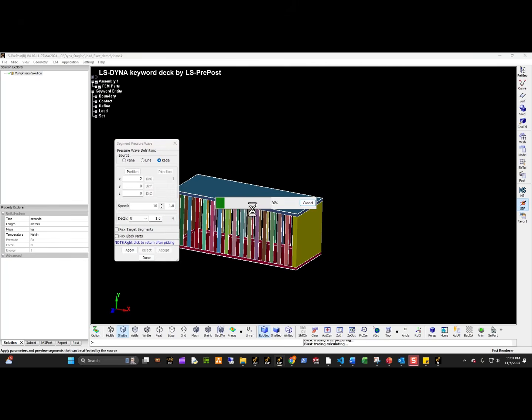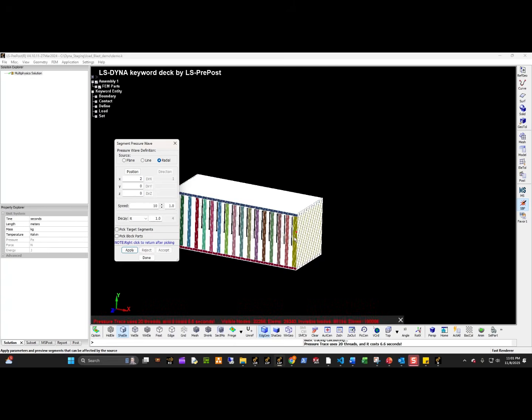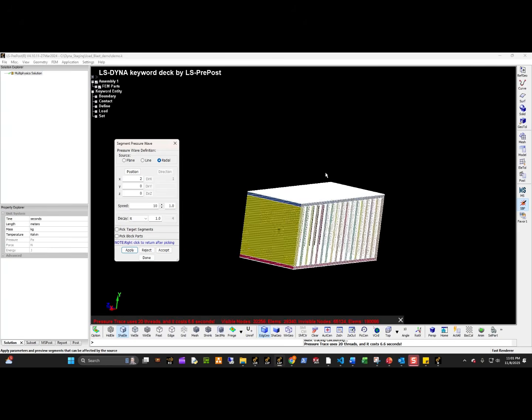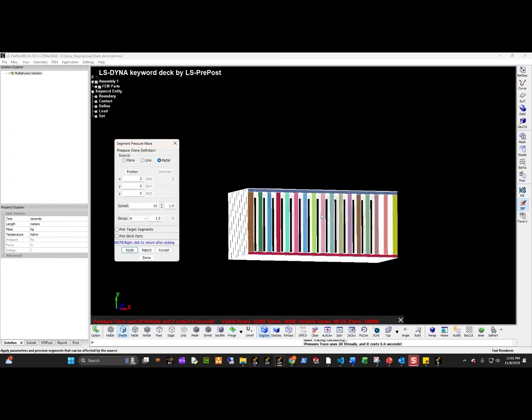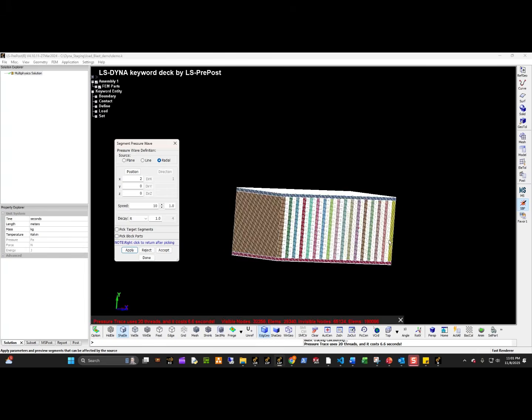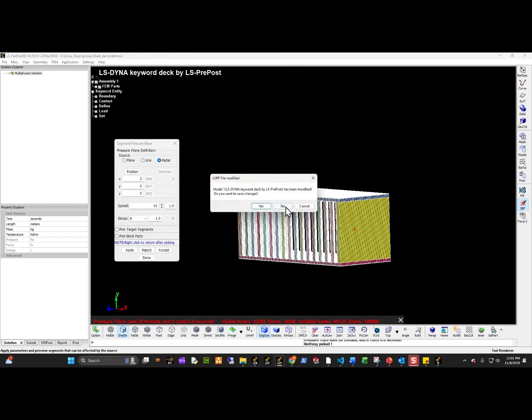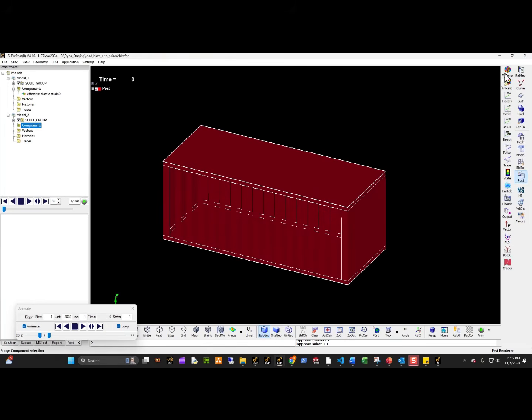What this is going to do is calculate all of the segments, from the perspective of the source of the blast: what can you see, what can you not see? So it reports invisible nodes, 32256 elements, that much, and invisible nodes that much. All of the invisible nodes will be on the outside, and it's something you can double check. Obviously, I was being lazy when I selected everything on the outside. You can select more carefully to see if certain segments can be seen by the blast source. So this tool right here is very useful for this kind of analysis. Okay, I'll cancel that.